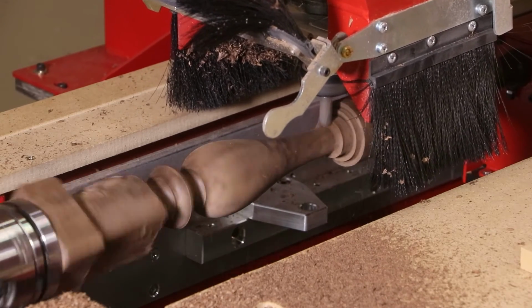So that leads us to a really cool feature that we can do. You use a CAD/CAM package, it doesn't matter what it is, right? I prefer Aspire. Okay, so let's say you're using Aspire. And you simply, instead of creating a model of what the turning is going to be and carving it, you just draw a 2D vector, just a 2D line that says, I want this shape. That's what I want. I'm just outlining it. Yeah, just outline it, not even the top and the bottom, just outline it, and then you save that G-code as a 2D toolpath. Now in Conversational CAM Pro, you simply import that toolpath, right? And it automatically converts it into a copy lathe. So now this functions like a copy lathe, just based on that 2D toolpath. Very, very simple and very fast.